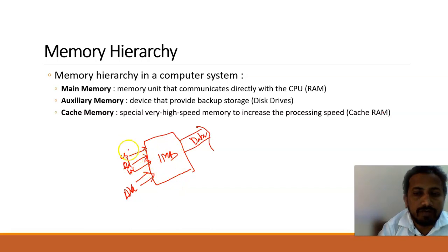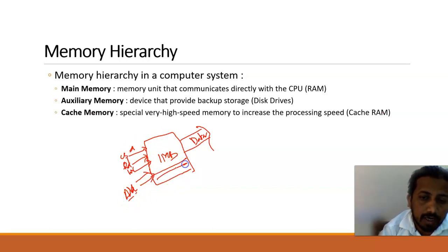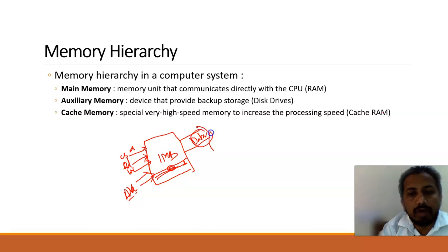Once you give chip select as high, it will select this memory. Then, given an address, the data at that address would be taken up. The number of output lines gives how many bits of data there are, and the address lines determine how many locations you can address. For 1 MB you would have 20 address lines, so you can address up to 1 MB.